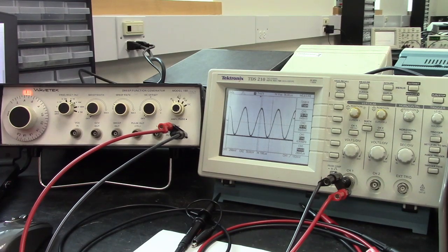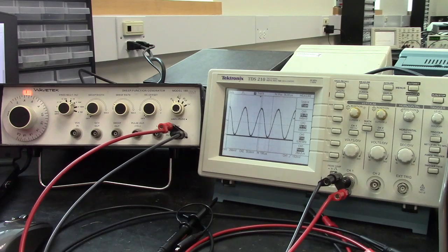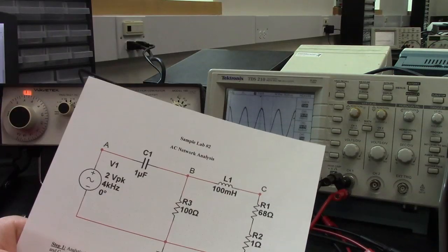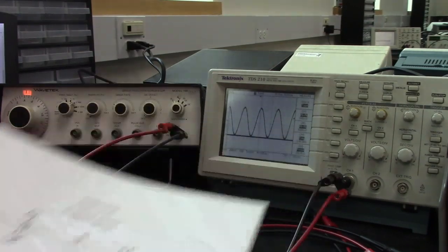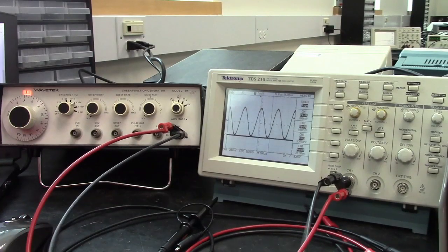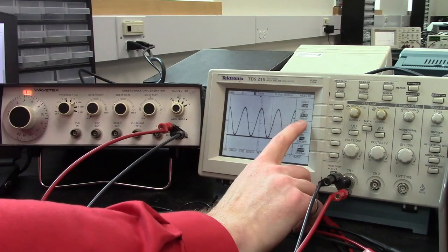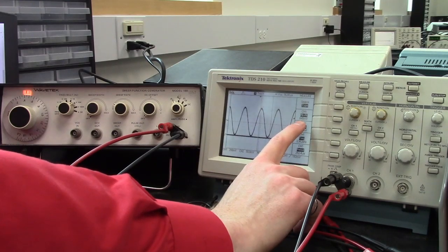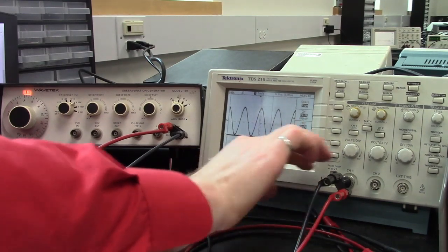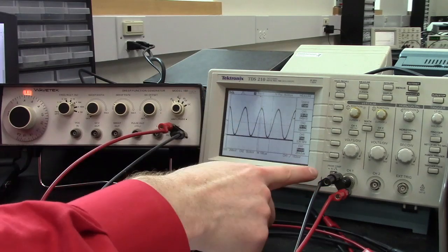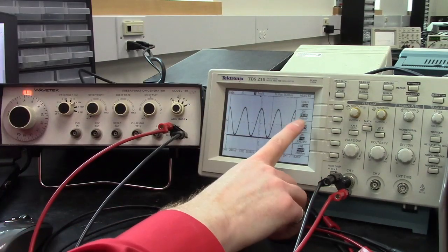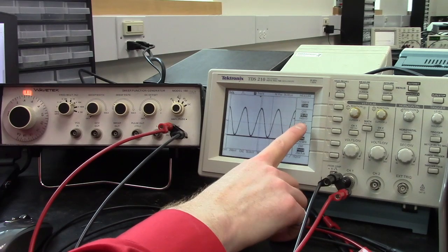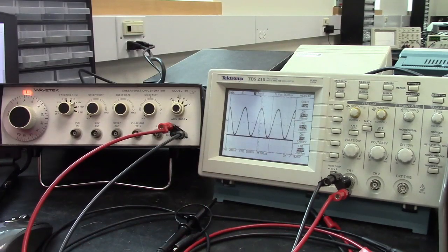So besides the frequency, the other thing that we want to get to the right setting is the amplitude. And we're going to need a 2 volt amplitude or 4 volts peak to peak. And right now, conveniently, that's measured on this output here. So we've got the channel 1, which is this channel here, the output from the function generator, reporting that its peak to peak is 848 millivolts. So we need that to be a fair bit higher.